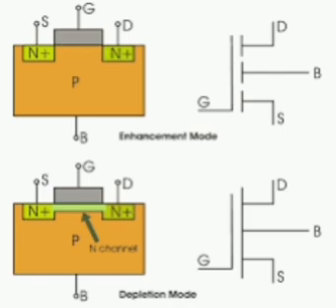Depletion width increases with reverse bias and decreases with forward bias. Depletion approximation is assumed in calculating the above equations. Charge neutrality equation: xn naught Nd equal to xp naught Na, also xn naught plus xp naught equal W.